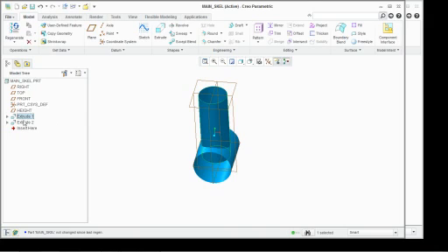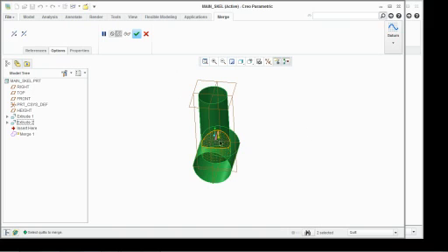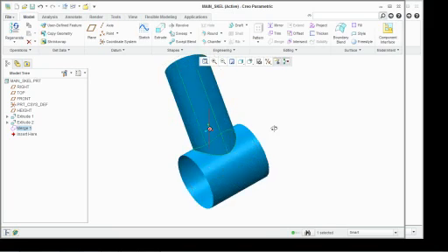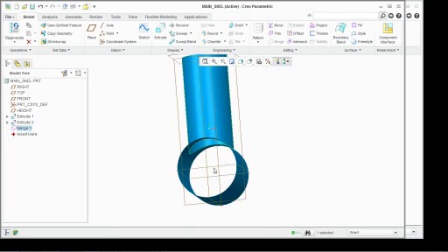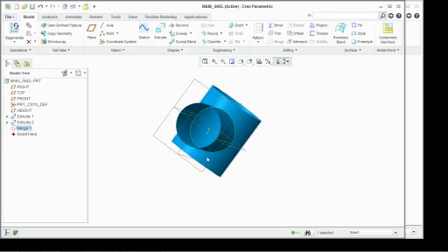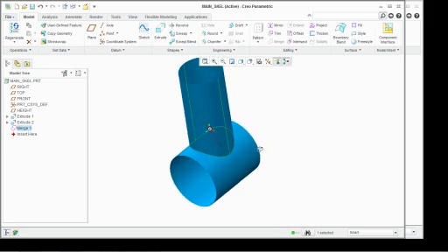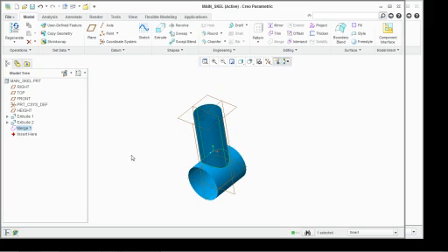So I'm going to take these two extrusions and merge them together. I've got my merge command right there, and I want to flip these arrows so that they're pointing those directions. Notice that that's the parts it kept. It cut the center out there, and down through here. Click to complete the feature. And if you notice now, it is one feature. It's blue because again it's skeleton geometry. And then I'm going to take this and do some work with it.